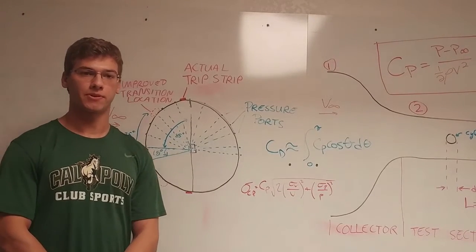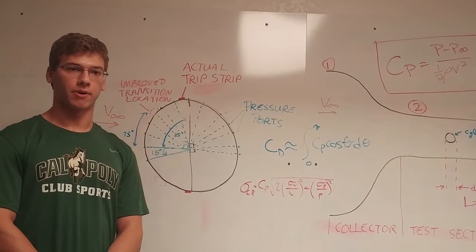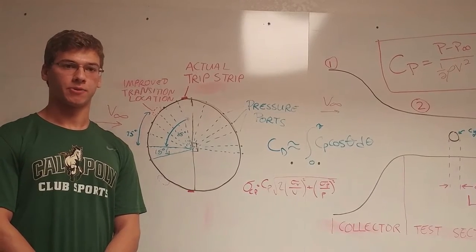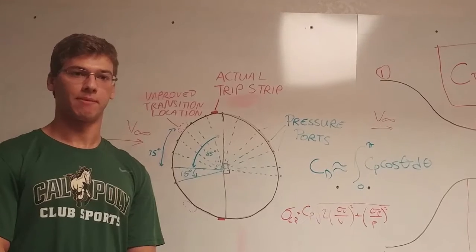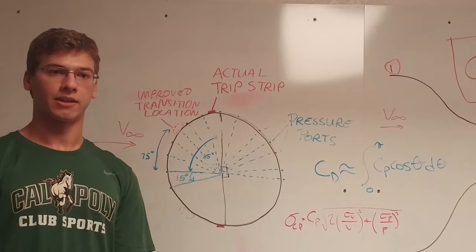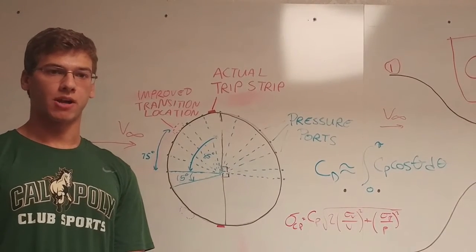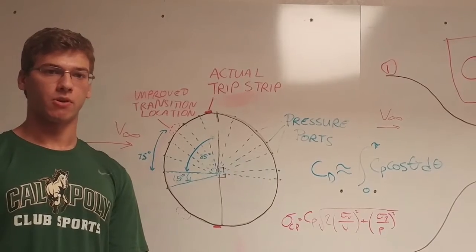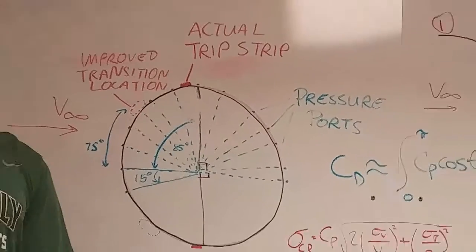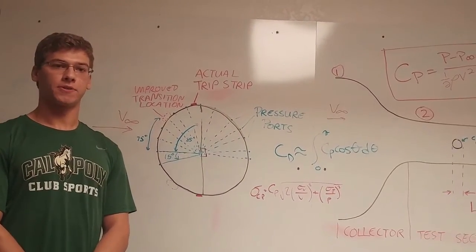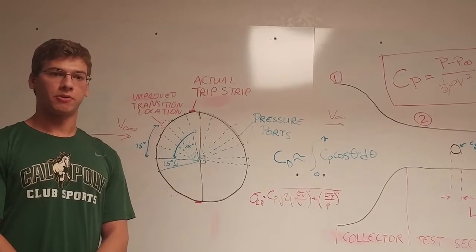It is important to note, as before, that for our Reynolds numbers, friction drag is not negligible. However, since we are looking at pressure in this lab, we will only be looking at the component of drag derived from pressure. In order to accomplish this, using our pressure data, we used a low-level panel code method. But since our CP values are already calculated with uncertainty and variation propagated throughout, we will take a more original